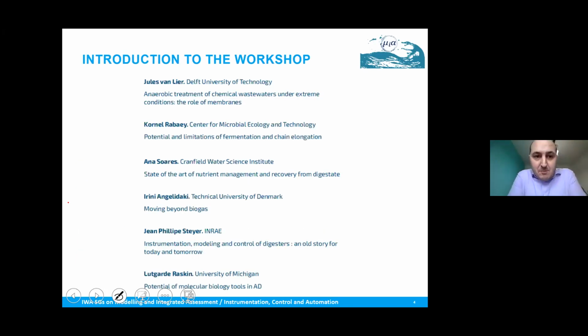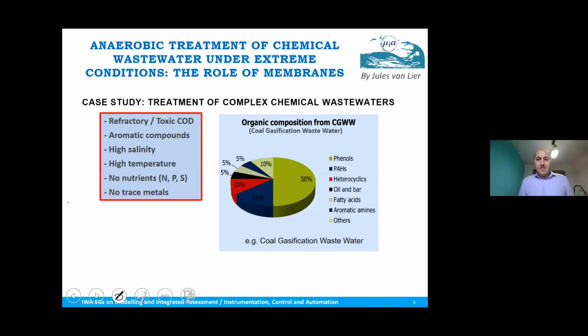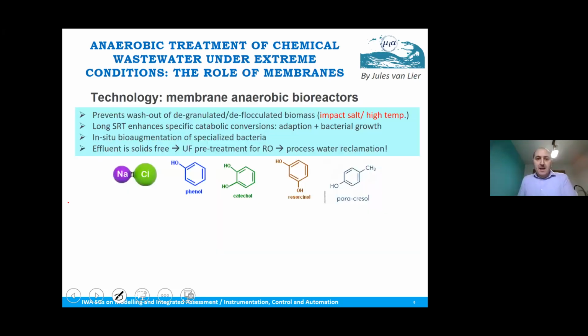The speakers of the workshop were Jules Van Lier, Cornel Ravet, Anna Suarez, Irene Angelidaki, Jean-Philippe Steyer, and Lutgarde Raskin. Jules Van Lier presented an overview on the potential of anaerobic membrane bioreactors for the treatment of complex chemical wastewater. He presented a case study treating a very refractory and toxic wastewater, mainly composed of aromatic hydrocarbons, at a high salinity, around 60 grams of sodium per liter, high temperature, almost no nutrients to support microbial growth, and no trace elements.